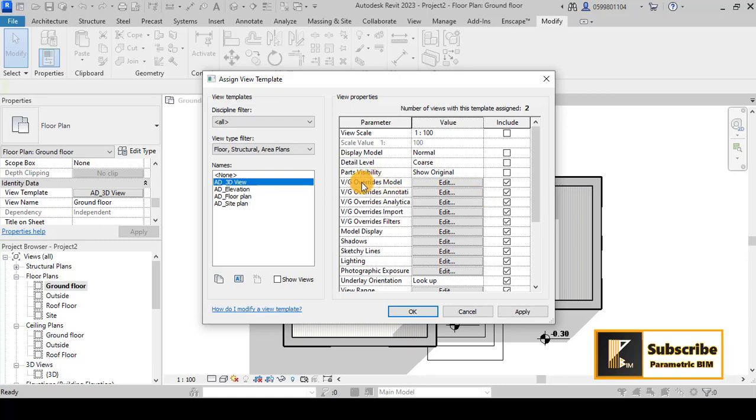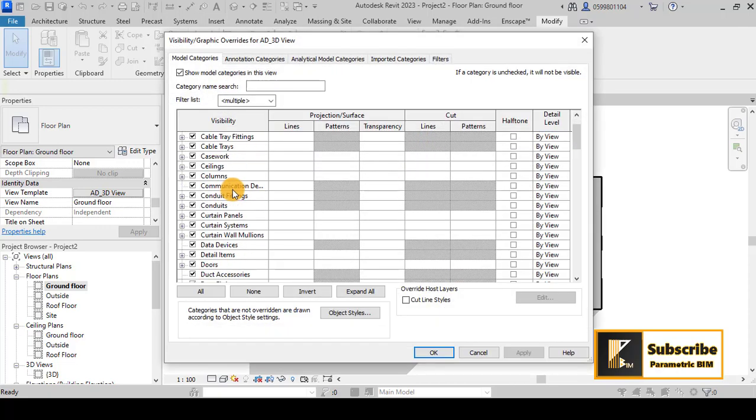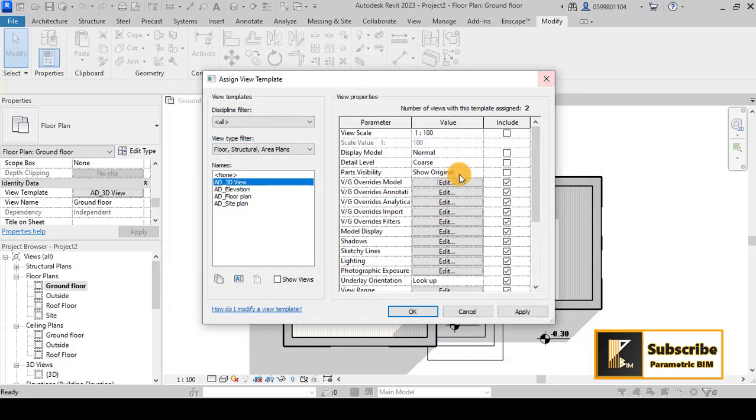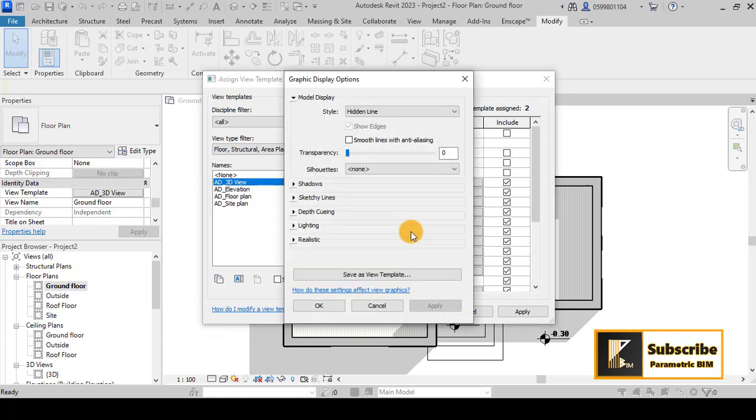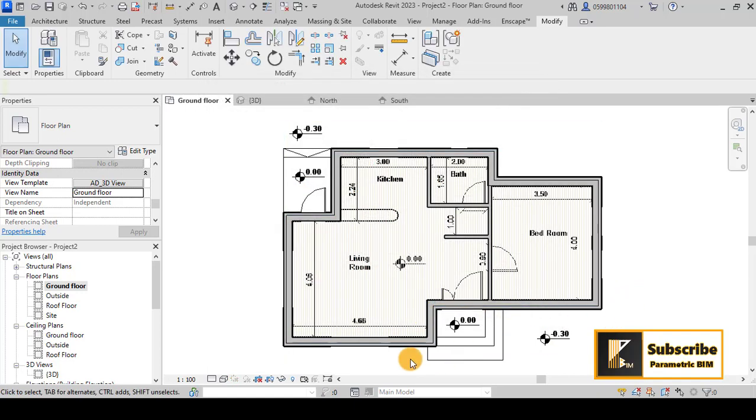You can also come here to visibility and graphics, or not visibility and graphics, you have to go to, let's say, not the annotation or analytics. You have to go to model display, and for that you can choose wireframe, and okay, you have now the wireframe.